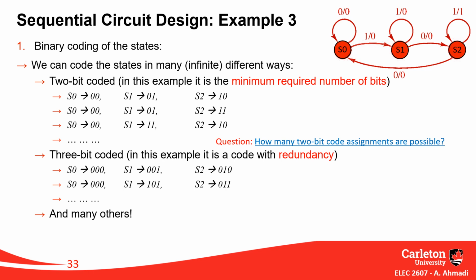Now, if I want to design the circuit, the next step is assigning coding to the states. Well, the S0 one coding will be this, as we do. Another one can be this for the original circuit, not for the Moore one, for the Mealy circuit, or can be this. I discussed that in class, and you know already. Or you can go for a higher number of flip-flops if you wish, with some redundancy.